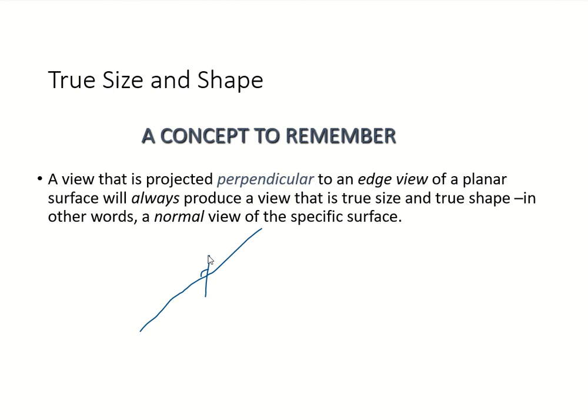This edge view, again, you're having an edge because you have a surface, a plane. So it can be that edge, or this edge, or this edge. Right now I'm taking this edge of this plane, even if I'm not drawing it here, because if I draw it, you're going to have confusion, looking at it from the front. So your line of sight is right here, straight perpendicular on that edge.